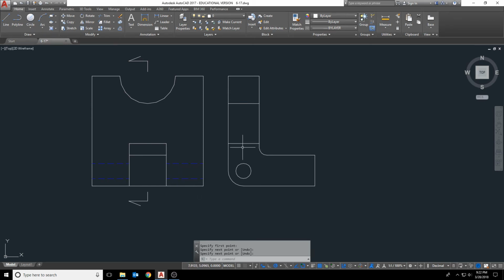Now, I know that this cut is symmetrical. On the top and on the front, it's the same distance. So just like we've kind of done before, if something is the same and it's perpendicular, we can actually mirror it on a 45-degree angle, and it'll give us the same result. So rather than measuring it out again, I can just mirror that on a 45-degree angle.